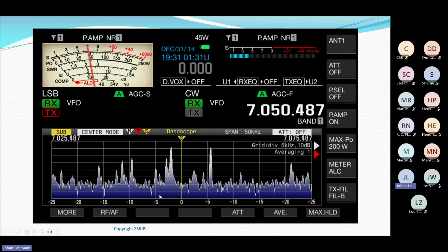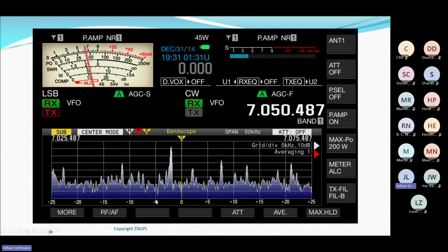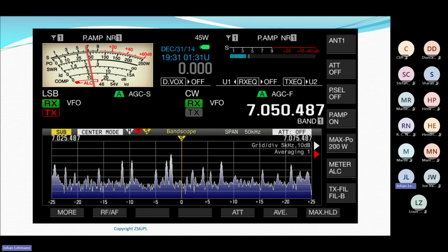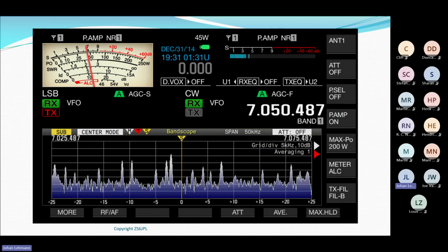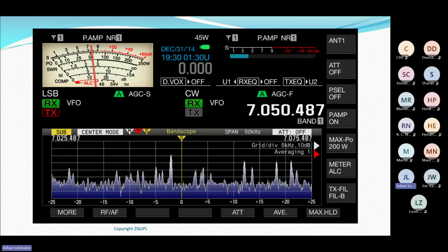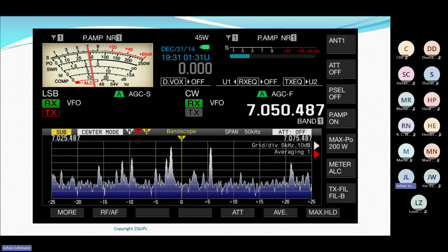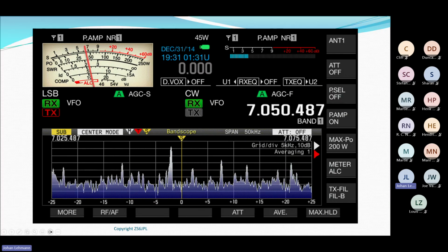And why I wanted to show you this, if you look at it carefully, remember what is the frequency range of audio that we use in communications, not in your hi-fi room, in communications. It's typically 300 hertz to 3.3 kilohertz. We only use about 3 kilohertz of bandwidth of audio when we modulate voice.